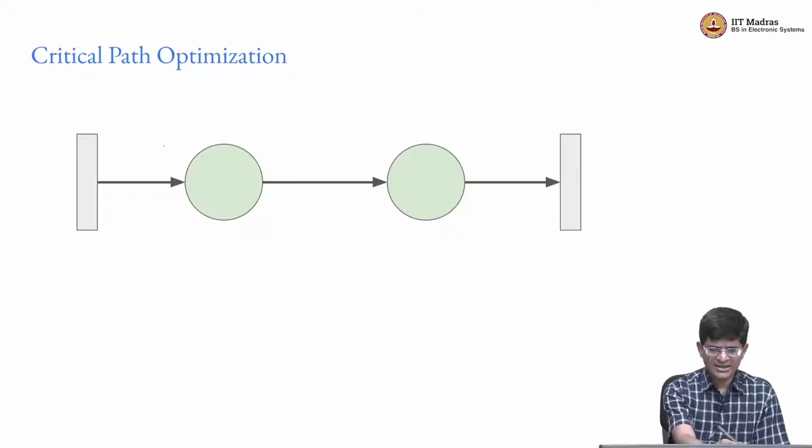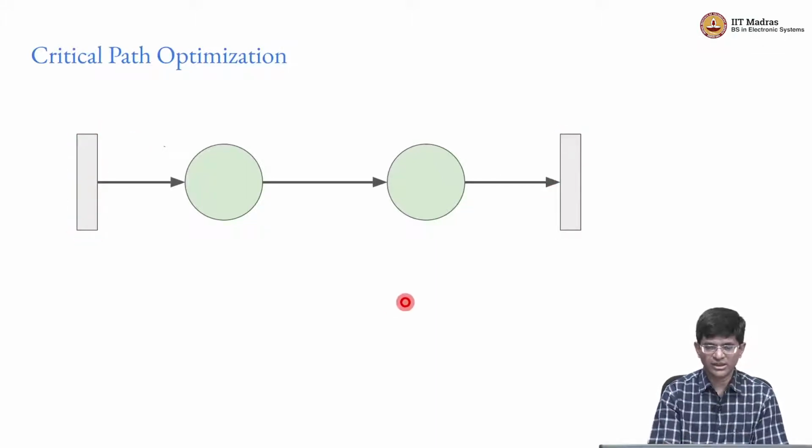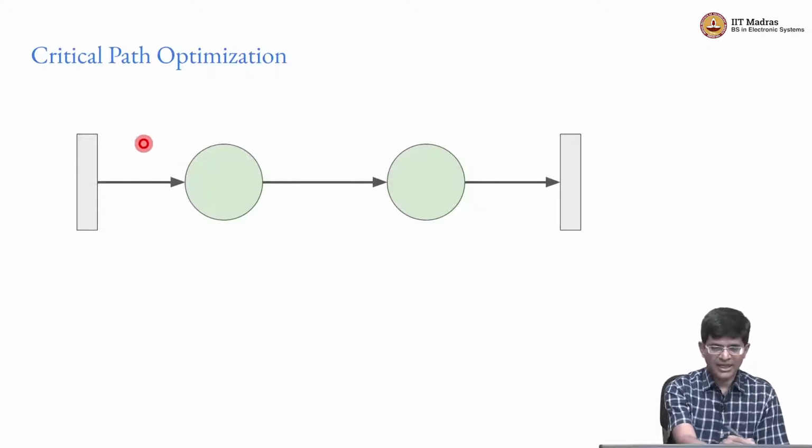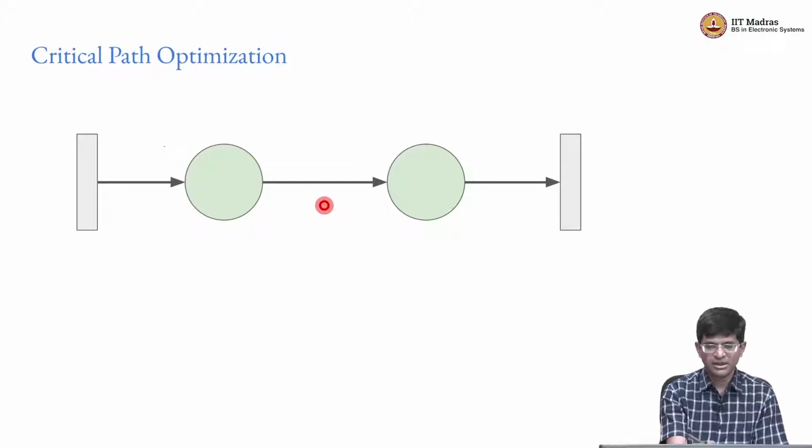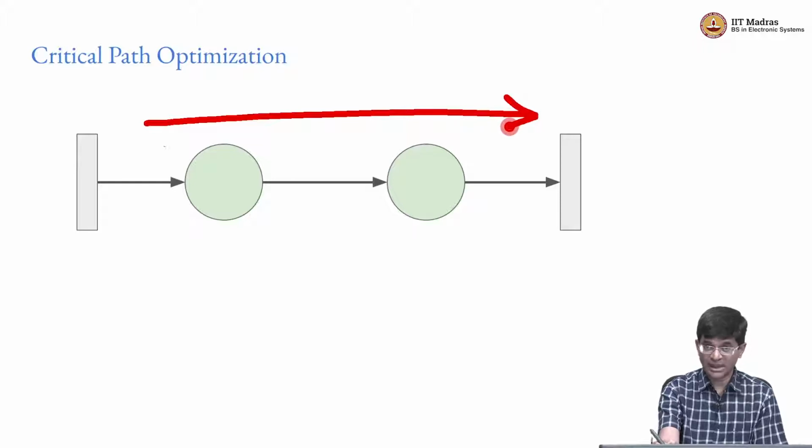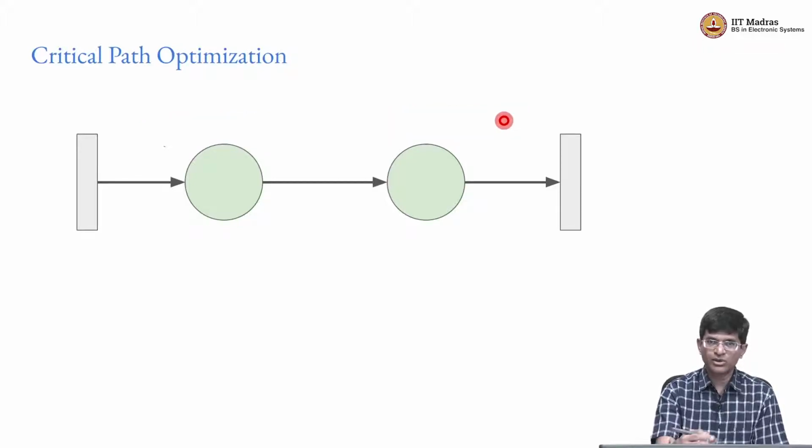So what exactly does this represent over here? Essentially what I have in mind is something where these gray boxes, the gray rectangles that you see over here, are registers, and the green circles essentially correspond to some kind of combinational logic. So as you know, essentially this is a path through the circuit. And of course what I have drawn over here is a highly simplified model which basically gives you the impression that there is a single signal passing through over here, some computation happening with it, that in turn gets forwarded to the next unit, again some computation happens, and so on.